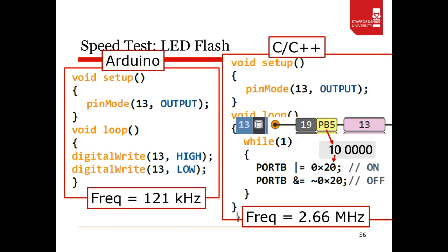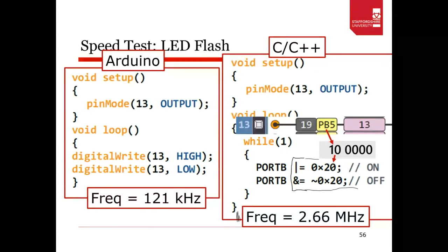I shall also show you later that we can shift to the left and shift to the right, but this is the easiest way, using the OR and the number, whether that be hex, decimal, or binary. I use binary because it's easiest for us to see where the number is coming from in terms of the bit on the port.